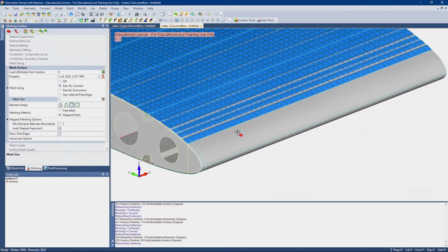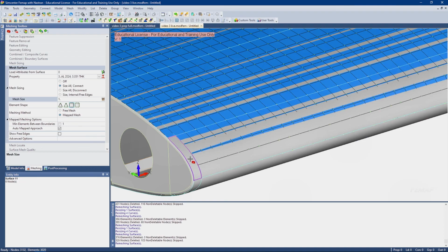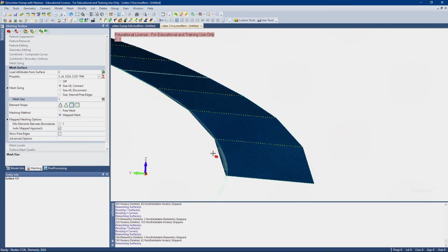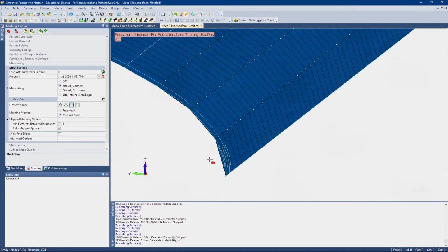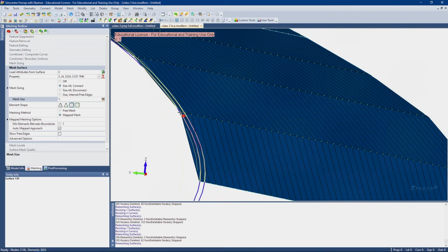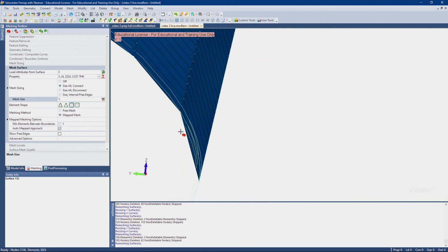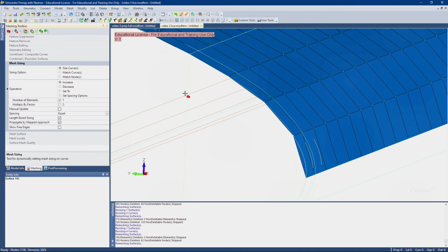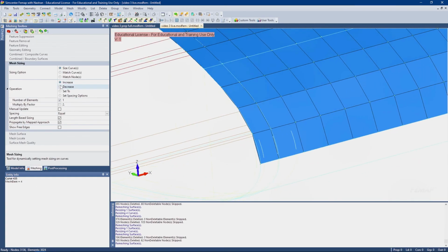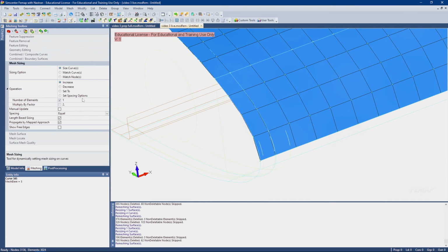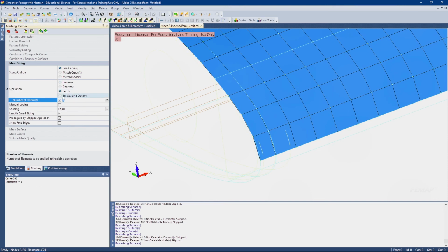Okay, so now here we could use 1 inch elements, but let me just turn off surfaces. You can see around the nose tip here where we have high curvature, here's where the elements are supposed to be following, and just because they're square elements, they kind of cut the corner and don't super closely follow the geometry that they should. So we're actually going to increase this density a little bit. Now essentially we have 4 elements here, 1, 2, 3, 4. So let's just do set 2 and let's double it to 8.